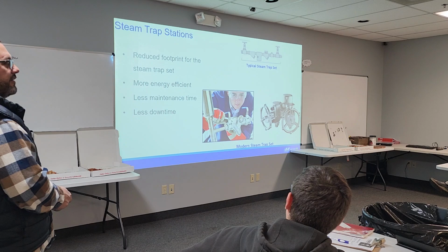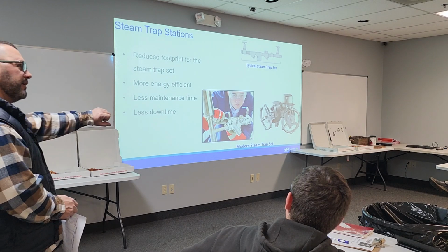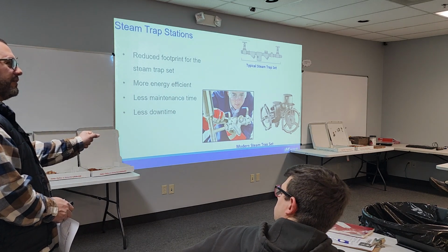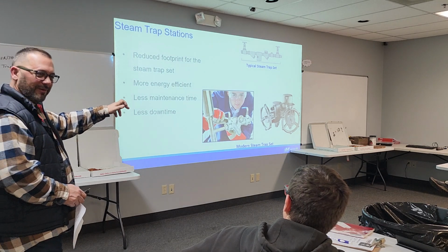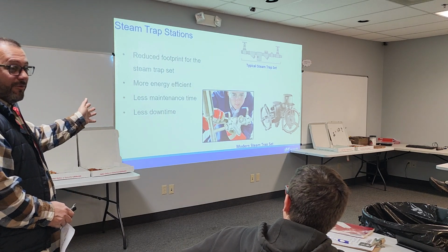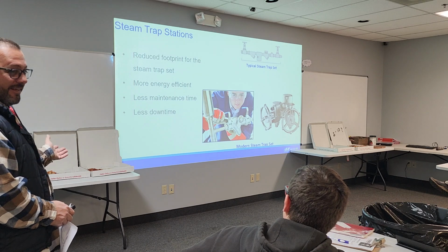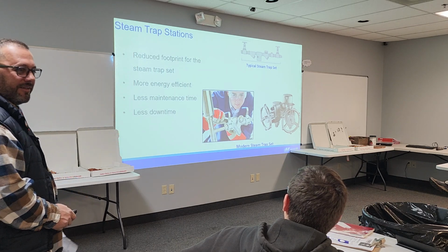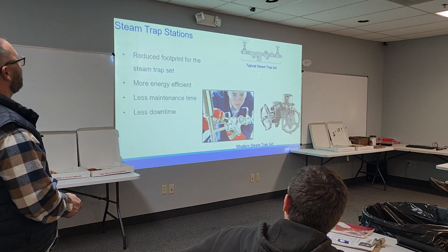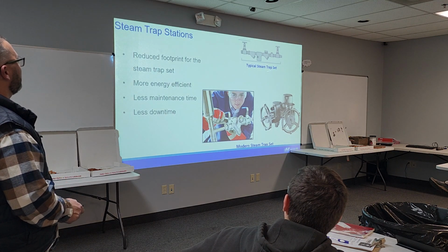We don't love ball valves just in the way that when you're opening steam valves, you want to do it slow. It's why they're usually multi-turn. Ball valves are great. They seal off wonderfully. They don't have packing like gate valves, but people like to open them up and close them really quick. And so this is just really meant to show you, this is a typical steam setup.